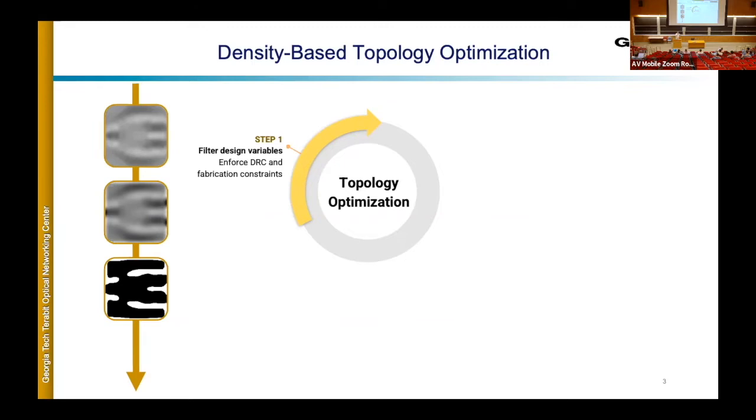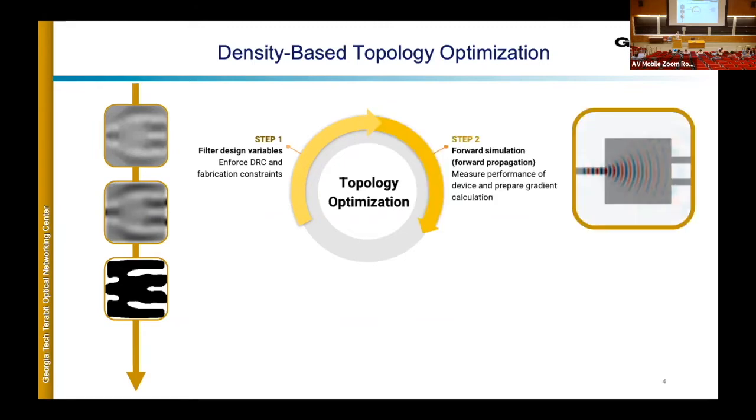But once you have your final device geometry, of course, you have to port that into Meep, and you have to simulate how well it's performing according to some arbitrary figure of merit that you, the user, care about. So in this case, we're going to be designing a silicon photonics splitter. So perhaps my figure of merit is how well I get that 50-50 split ratio, right? And you can see I'm just propagating my broadband pulse through that arbitrary geometry so that I can evaluate that FOM.